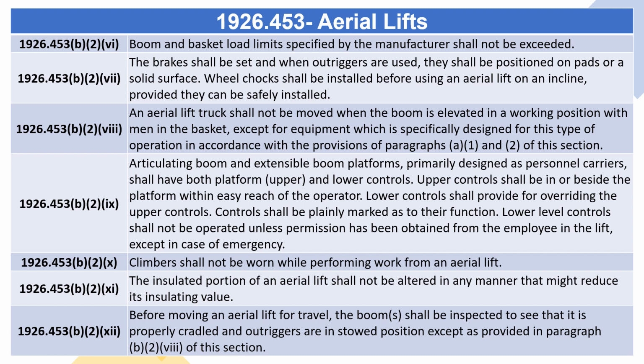An aerial lift truck shall not be moved when the boom is elevated in a working position with men in the basket, except for equipment which is specifically designed for this type of operation in accordance with the provisions of paragraphs (a)(1) and (2) of this section. Articulating boom and extensible boom platforms, primarily designed as personnel carriers, shall have both platform (upper) and lower controls. Upper controls shall be in or beside the platform within easy reach of the operator. Lower controls shall provide for overriding the upper controls. Controls shall be plainly marked as to their function.